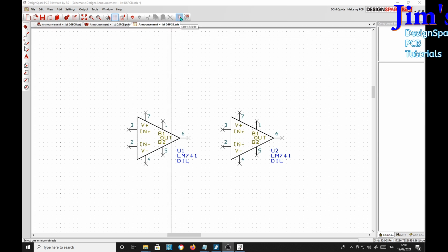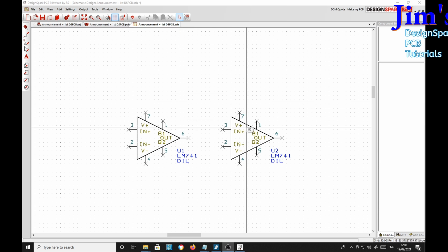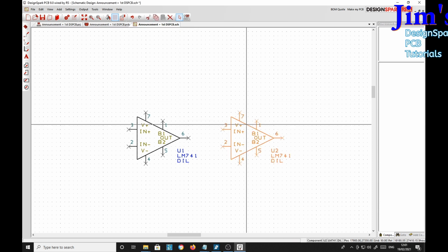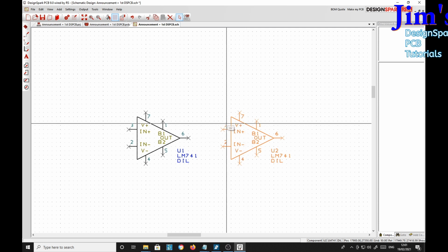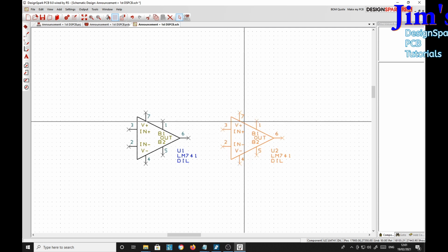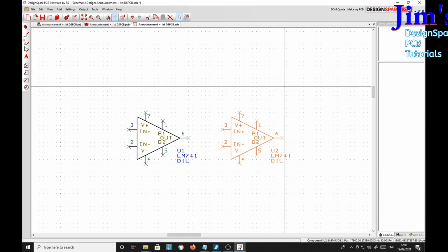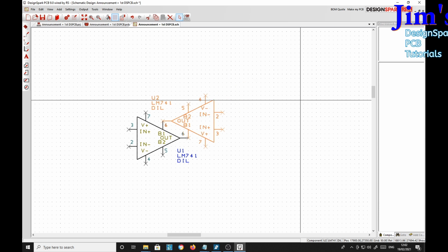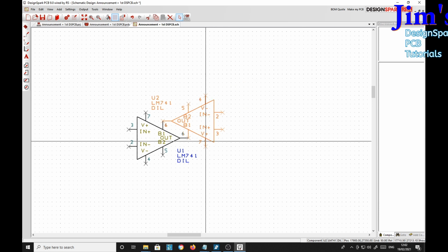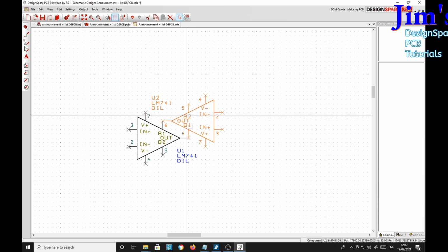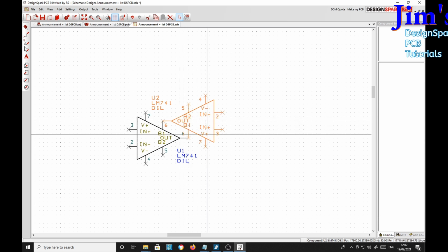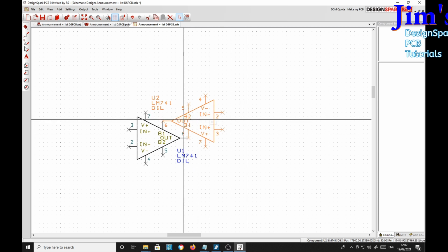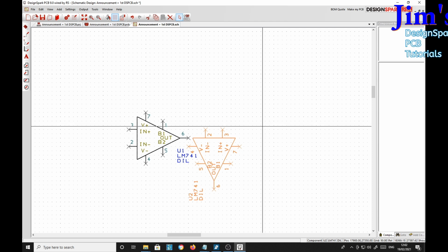So we're in the select mode here, up at the top, so I can select the whole of that IC by clicking on this outline, and by pressing the R key we can rotate the thing, and it's showing that the text is always readable by being either left to right or bottom upwards.